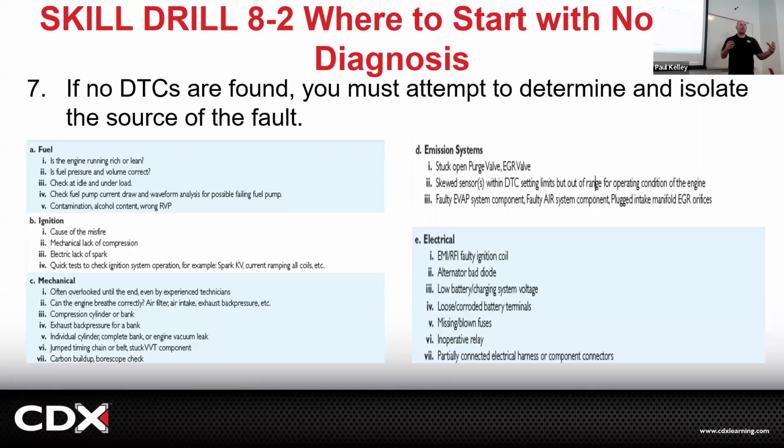But see, we're mostly going off of our own understanding, right? There's no flow chart for this. There is none. Okay, so this is the more advanced diagnosis. It's still the onboard diagnostic system because we can look at fuel pressure sensor information. We can look at oxygen sensor. We can look at stuff, but then it's also kind of old school. You're actually checking fuel pressure. You're measuring this. Maybe the injectors are dirty. Maybe your fuel pump is worn. It's not really making enough fuel pressure, right? So the reason I like to cover this now is you need to understand how all this stuff works together if you want to actually be able to do the no code diagnosis.